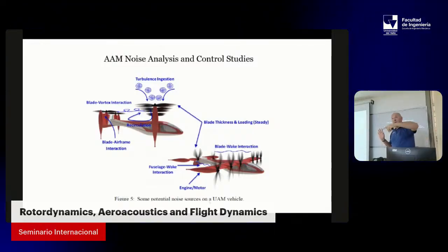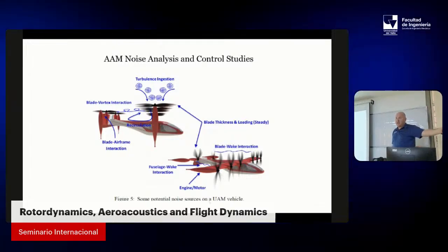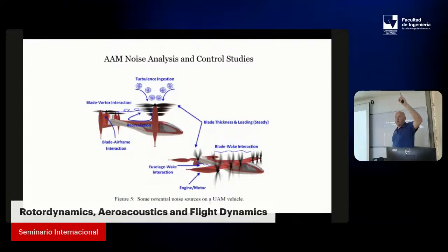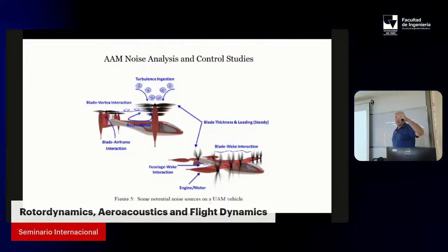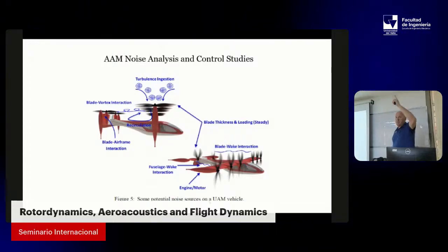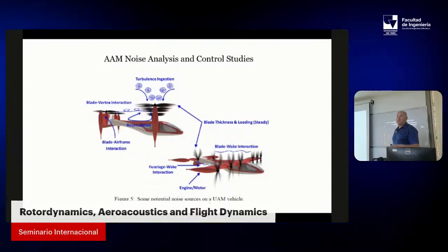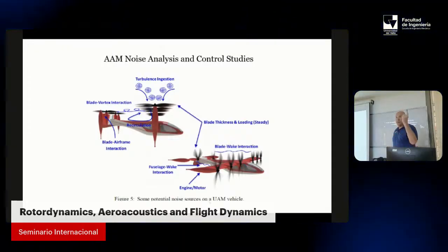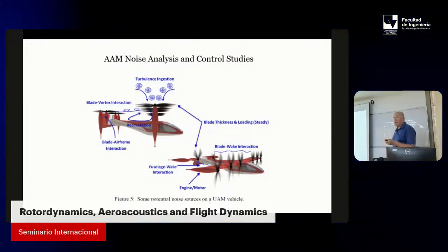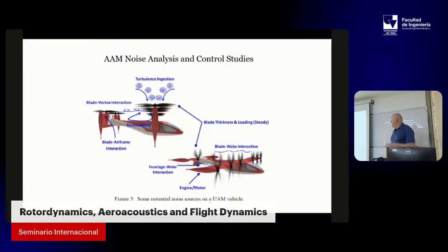Because it moves, you have the first frequency tone as an observer located at a stationary point, and this loading is rotating now. You have something called the BPF tone, blade passing frequency. That relates to the RPM of this rotor, right? So that's the BPF tone, the primary tone for all helicopters. That's what you typically hear with a single rotor. That's the typical thing for helicopters, which you hear when it flies over. It's a BPF tone. But then,